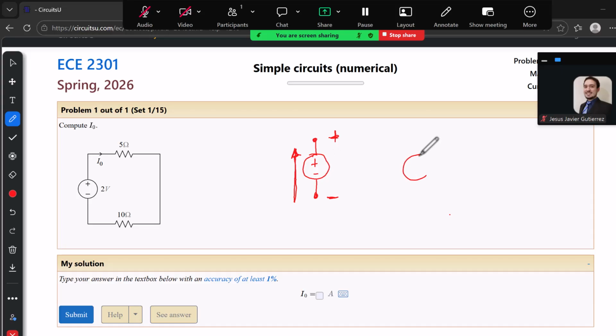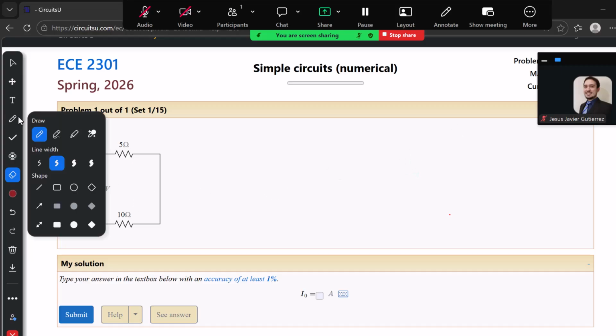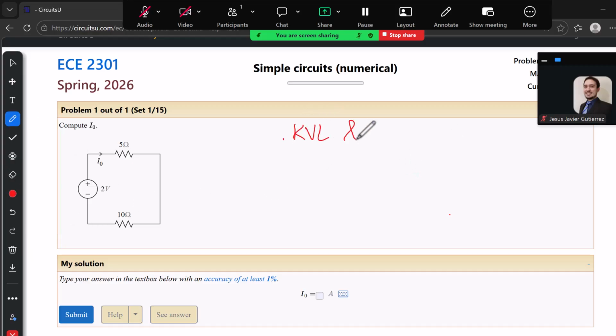Now, if we have a current source here, let's say a terminal here, then the current is already given, but by the passive sign convention, sources are deliverers of power. They deliver power to something else. So in this case, their power or their sign must be negative. And so we can assign plus and minus terminals here so that it goes with the passive sign convention. Now, with this explanation in mind, I will lead you to the last thing, which is KVL and KCL.